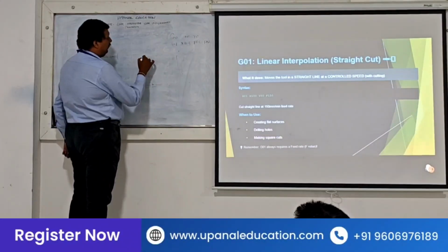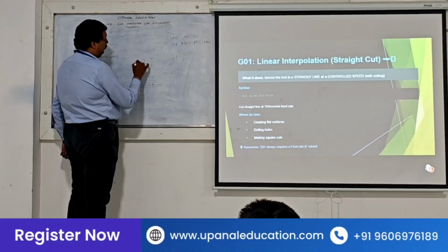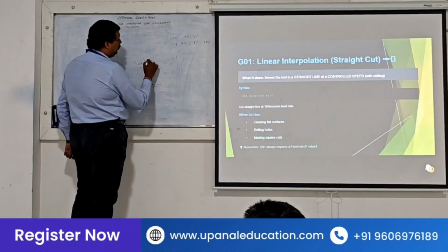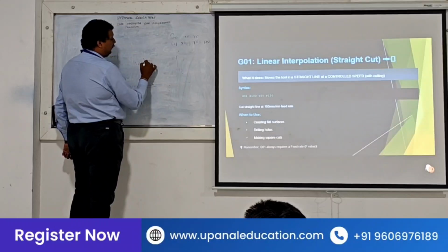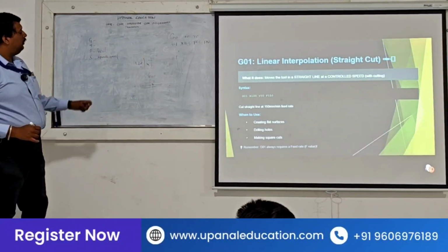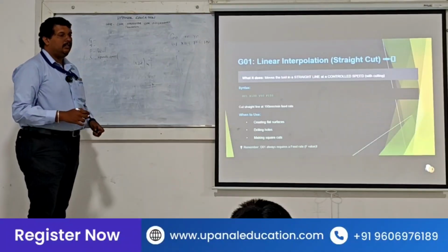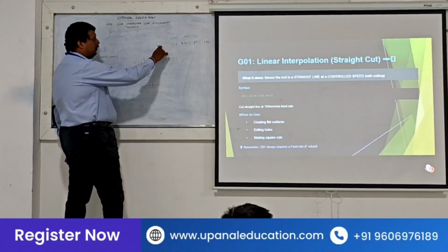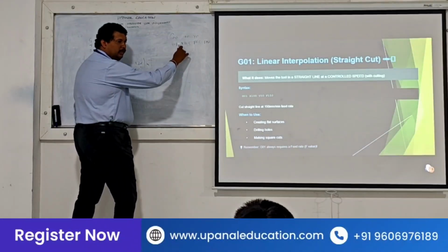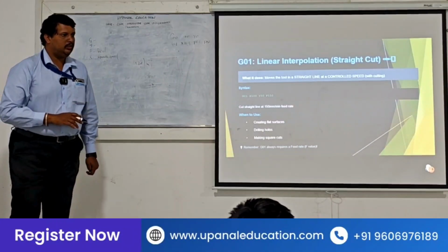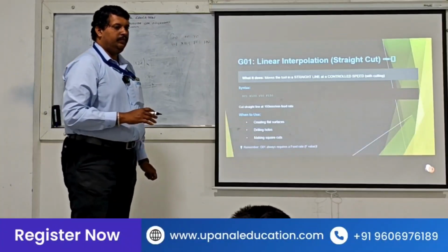The height is 12 mm. I want to reduce the height to 10 mm. So that time I will use G01 and tell it, go from here to here, then come back from here to here, go from here to here. All those things will happen. Understood? G01, you understood? Any doubt?